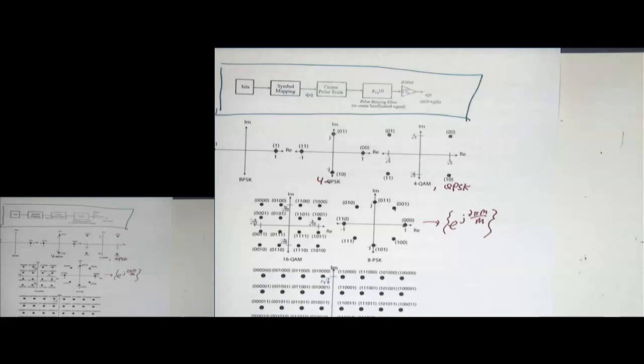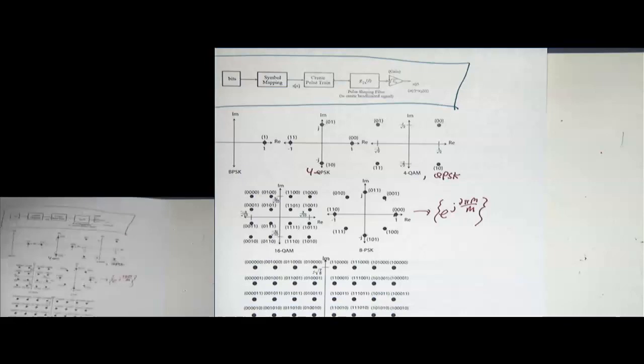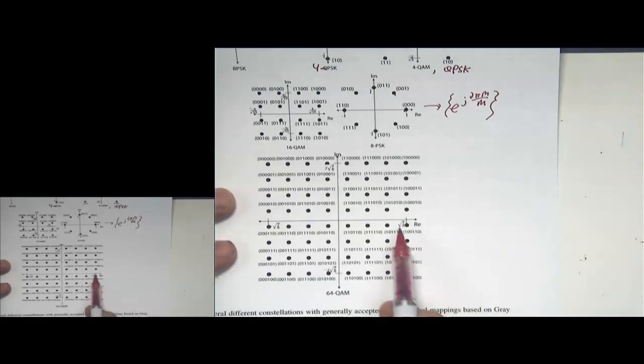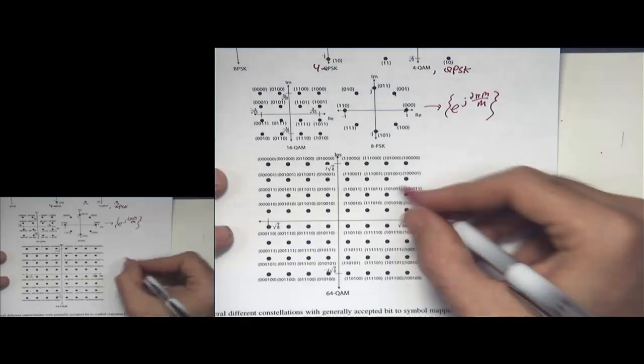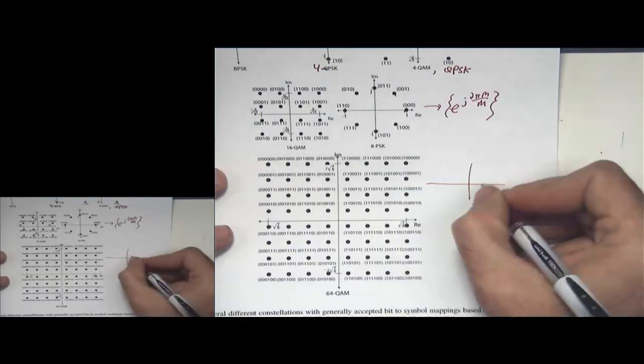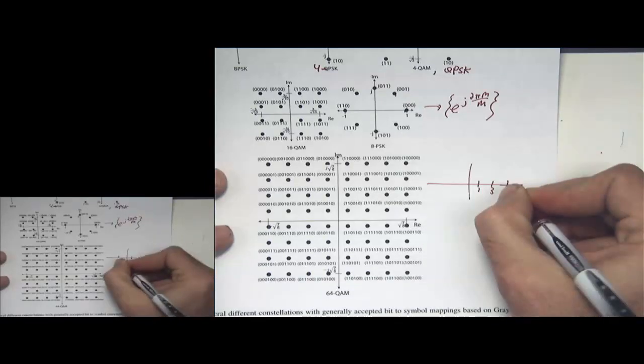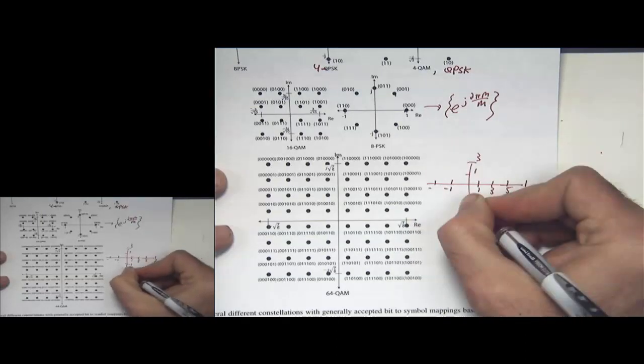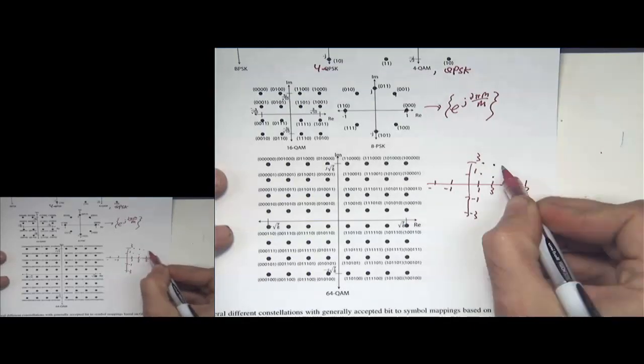The difficulty here is the normalization, because normally when we talk about QAM, if I was to zoom in, you can possibly see it here. There's a square root of 7/6 here. I got this from applying the normalization, but normally if you open up a book, you would see the 64 QAM spaced like this: 1, 3, 5, 7, and -1, -3. This would be 1, 3, -1, -3. So this is normally how the points would be specified.